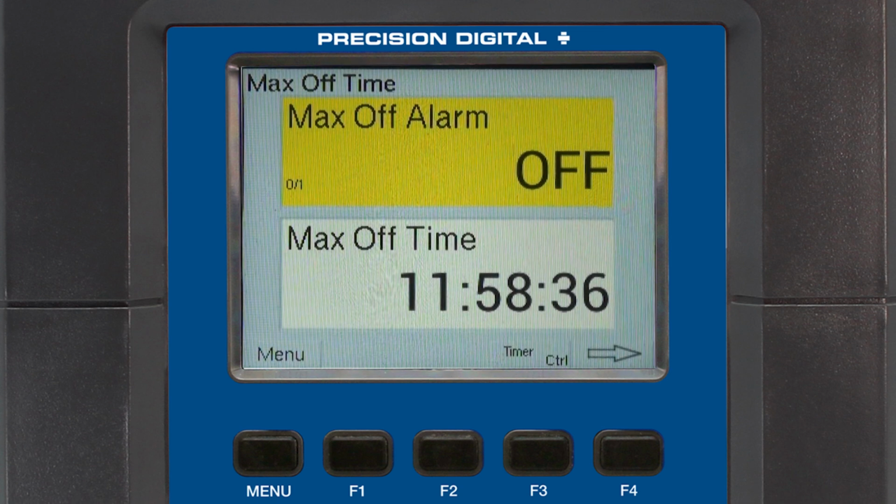In some low flow stations, significant time can pass between pump cycles. This can mean that odorous liquid is present for an extended amount of time. For that reason, a user can configure an amount of time that will call the next pump to run. A pump will only run if the low float is closed and will run until the low float opens. When the pump turns off, the timer resets and the cycle starts again.